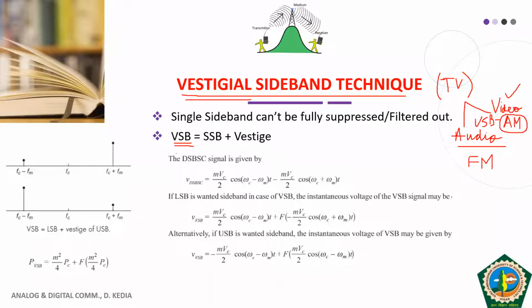Just now we talked about single sideband, students. We had two sidebands earlier. In single sideband, we removed one of the sidebands completely, and we were left with only one sideband. Now in vestigial sideband, we do not remove the other sideband fully.